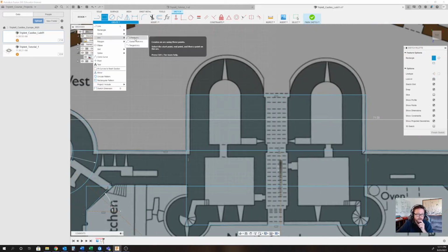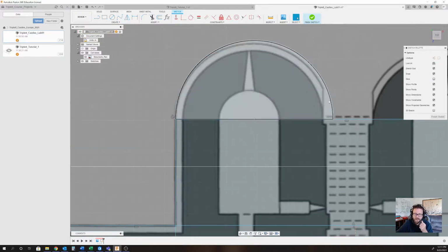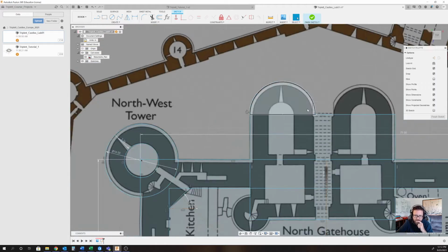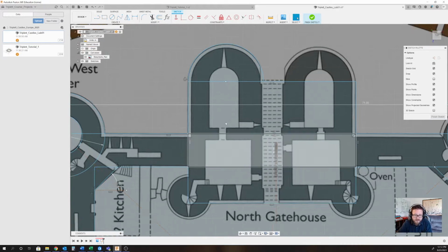I'm going to create a 3-point arc from here, and I'm going to guess where this one comes down. Maybe there. That's probably a little off. But what I haven't shown you is you don't necessarily always have to click the constraint. It's going to lock in if you're really close. So I'm going to stop that right there. And since this point was already colinear, I can pull this in and just adjust it later, and it's always going to stick to that line, which is nice. Colinear is another one of our constraints that you usually would use with points. Okay, that's a good start.